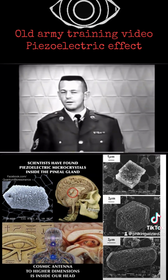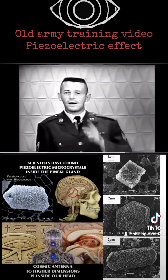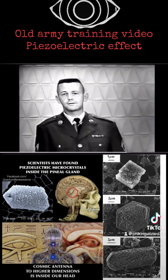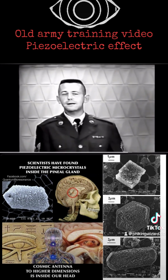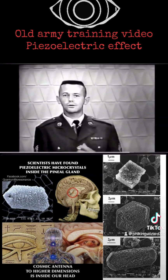Now, just because this vibrating crystal is the equivalent of a series LC tank circuit, I don't want you to think that it's the same thing, because the crystal will be far superior to the LC tank circuit. Now, the Q of the crystal circuit is many times greater than that of the LC circuit. Let's take a look at the comparison between the Q of a crystal and an ordinary LC tank circuit.